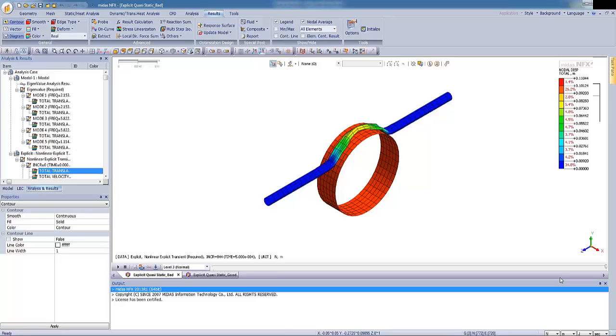After this, we have to estimate the global deflection in the impact direction. In our case, it will be 0.1 meter. When we have them, we can calculate impact velocity from a simple formula: distance divided by time.